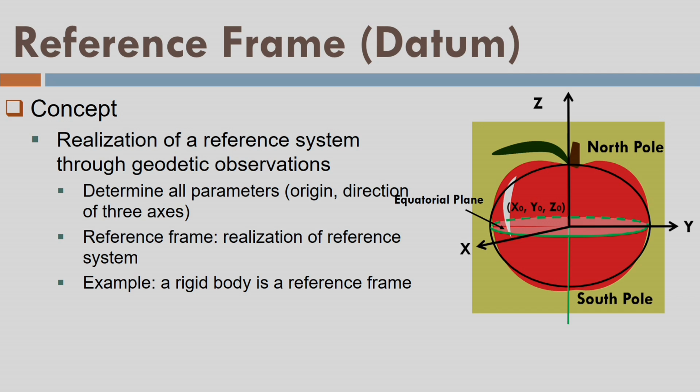So this kind of arrangement we always consider, and then we say let us assume the earth is a rigid body. Now let us see, there is a reference system or a reference frame XYZ with origin at x0, y0, z0. So let us fit a reference ellipsoid to that surface, centered at the origin of the reference frame. I call it the equatorial plane, which is shown by a green circle here. Fine, and this is my rotation axis, and the rotation axis is cutting at the north pole and south pole.